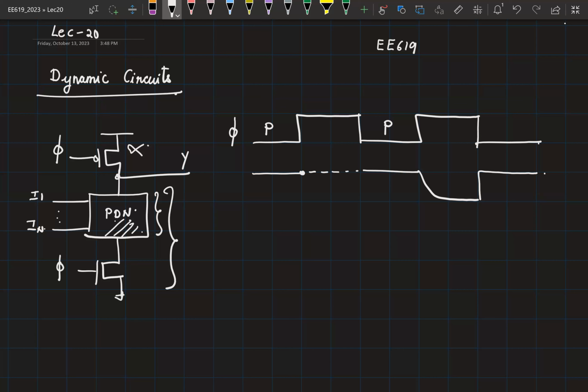Okay, so we did this analysis assuming that the output capacitance did not have any leakage. What happens if there is a leakage in the output capacitor? So during this stage, because there is nothing to reinforce it back to VDD, this can start to leak. Now, if the leakage is severe, it might cross over the midpoint voltage of the next logic gate. So now this is a serious problem, right? Because your functionality, the output itself can change. What is the solution?